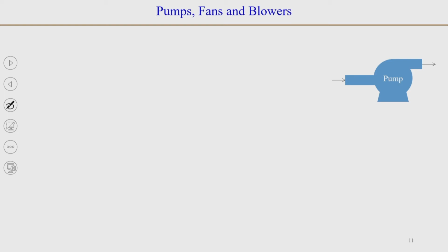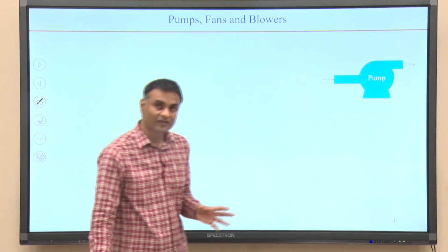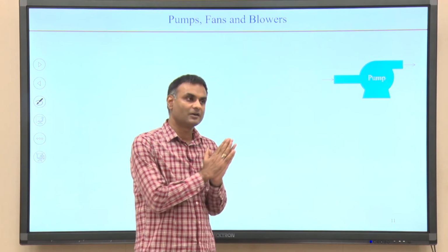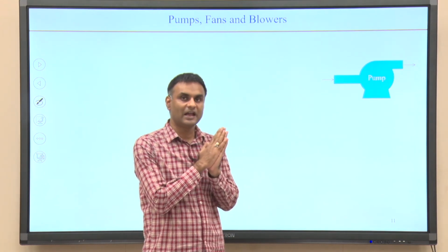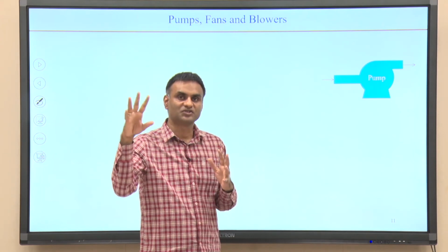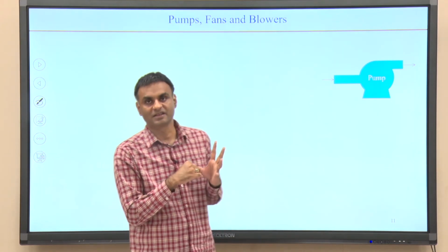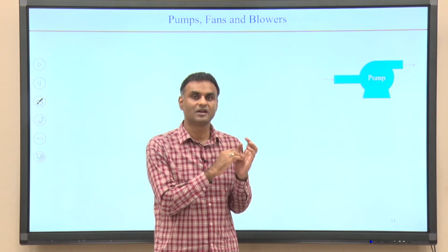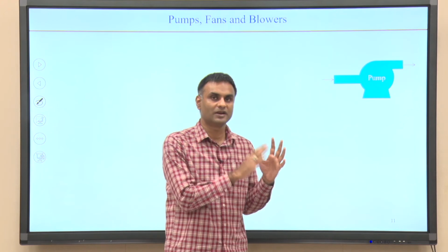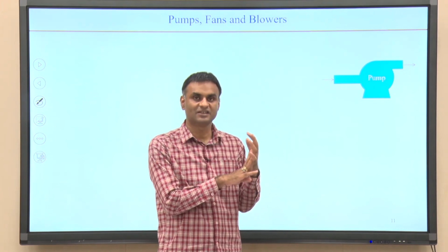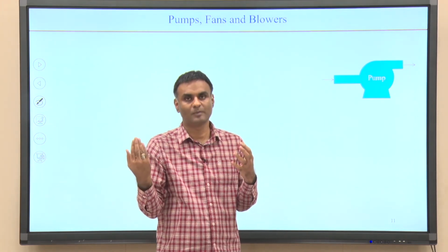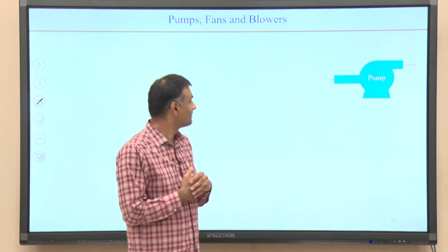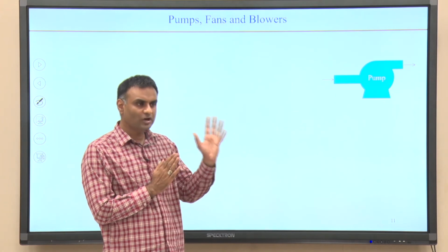Okay. So, we talked about different minor loss components and what causes the minor losses. It can be represented as K V bar squared by 2, and this K is the loss coefficient. This loss coefficient we can find out, or we can look into the data sheets. If we are talking about solving problems, then generally it will be given as part of the problem. Now, we talked about losses.